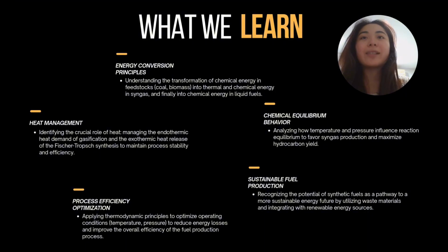First, we gain a solid understanding of energy conversion principles, how the chemical energy locked inside coal or biomass is transformed first into thermal energy during gasification, and finally into the chemical energy of liquid fuels. Second, we learn about the critical importance of heat management. We have to carefully balance the endothermic heat requirement of the gasifier with the massive exothermic heat released from the Fischer-Tropsch reactor. If you don't manage this heat properly, this process becomes inefficient or even unsafe.